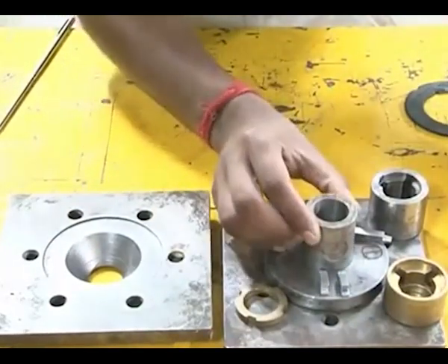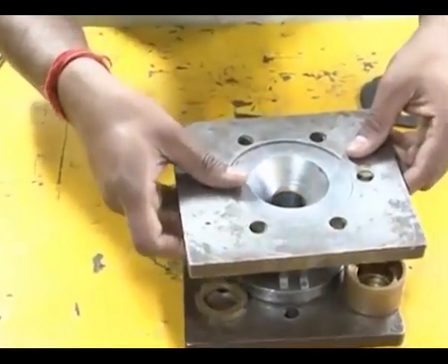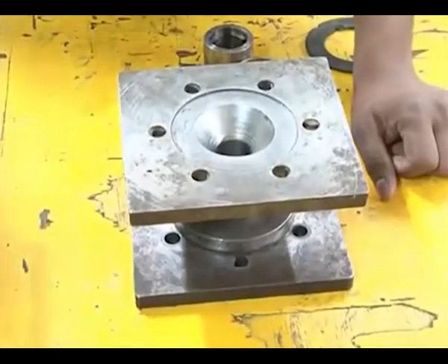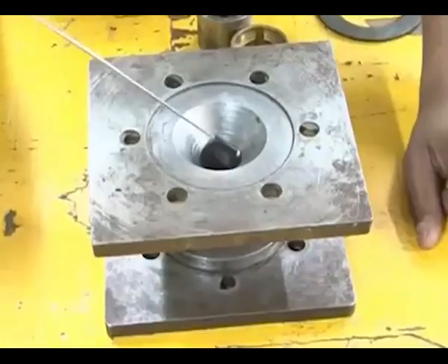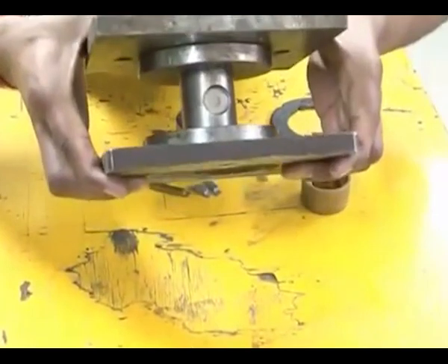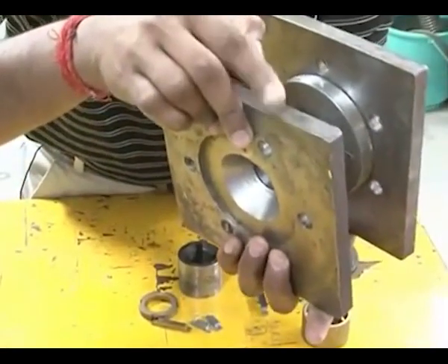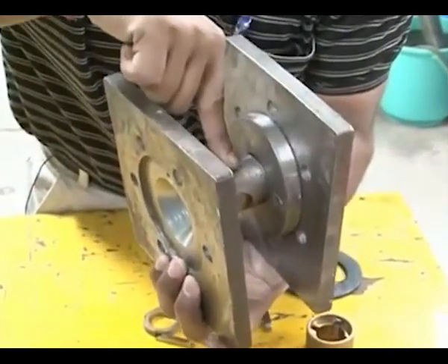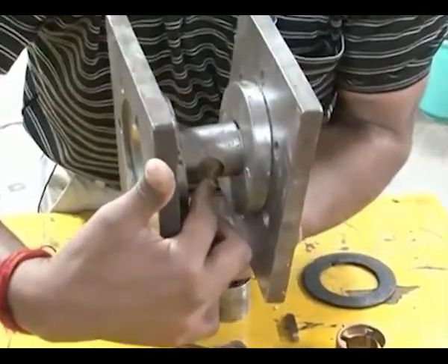You will place this workpiece like this, and you will place the bottom plate like this, and this completes the tooling. And now the medium flows from bottom cylinder to the top cylinder gradually through this tapered portion. This is the assembly of abrasive flow finishing process, wherein this is the bottom fixture plate and this is the top fixture plate, and this is the workpiece that we are finishing, and we can sense the acoustic signal from this hole.